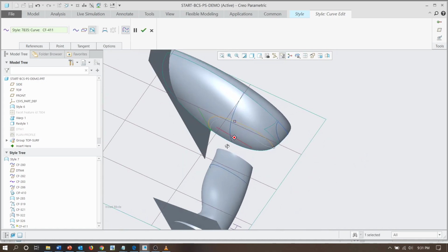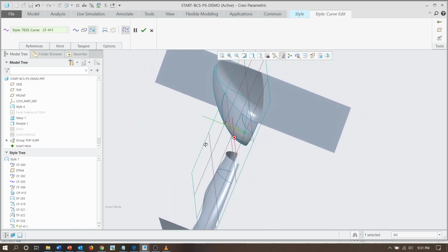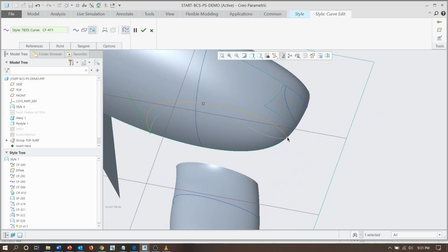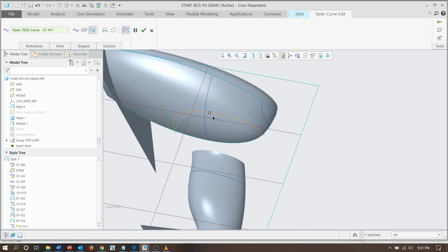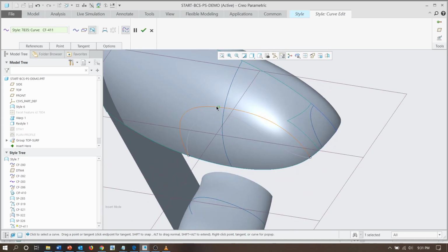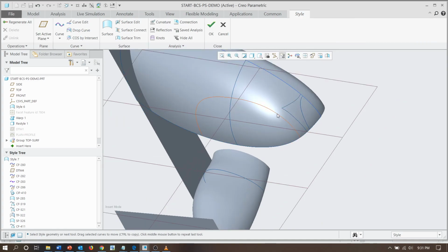Let's just make sure that once we mirror this part, it'll transition smoothly into the other side. And then this middle point I can use to adjust the direction or adjust the position of the curve on the surface. So these two curves that I created will be our boundaries, right? That will serve as the location for the boundaries for the surface that we're going to create.